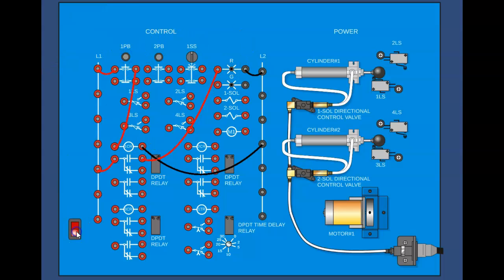Now, I want you to look at the flip side of this, which is the normally closed contact. And we're going to come out of it. Now, we're already bringing power in. This power is switched either through the normally open or the normally closed. So whatever I put on this pin is either going to go through this path or this path, depending on the state of the relay coil. So we're going to come out of there, and we're going to go to our green lamp. Now we've got to add our ground.